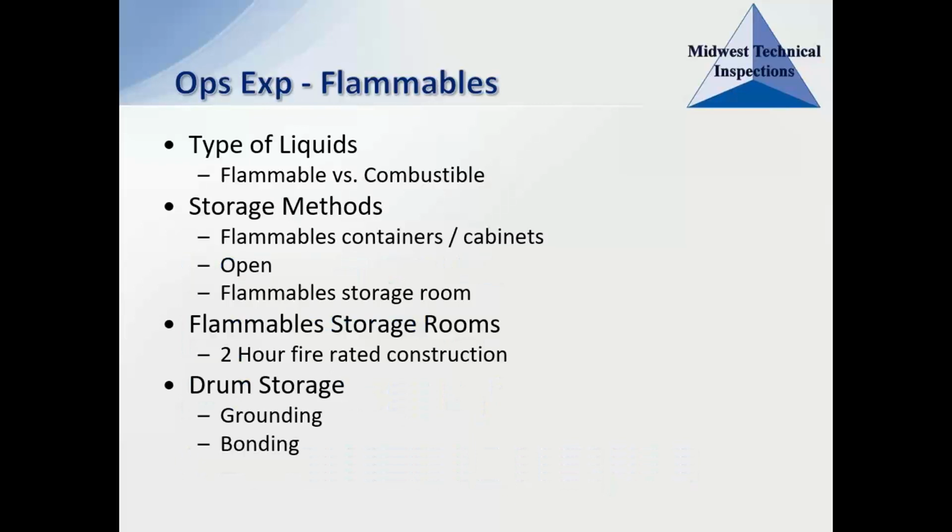Flammable combustible liquids, of course, you need to identify whether it's flammable or if it's combustible. So what types of liquids are we dealing with? There's a huge difference between a flammable and a combustible, and that difference is going to be the flash point. At what point does it ignite? What temperature does it ignite? So if you have like a bowl full of gasoline, which is a flammable, it has a very low flash point. If you take that bowl full of gasoline, you light a match and throw the match at it, well, it can actually erupt into flames. It's such a low flash point that it will ignite easily.